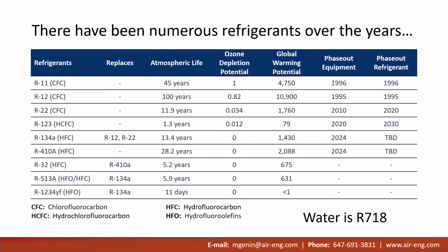Frankly, many refrigerants were used for non-HVAC applications like spray foam insulation and aerosols over the years, and these are a one-time use product, and these refrigerants were used to propel foam or the spray can product. HVAC is a small portion of the overall refrigerant use globally. So when choosing the correct refrigerant for the HVAC industry, power consumption or the efficiency of the cycle needs to be considered over the life of the equipment.